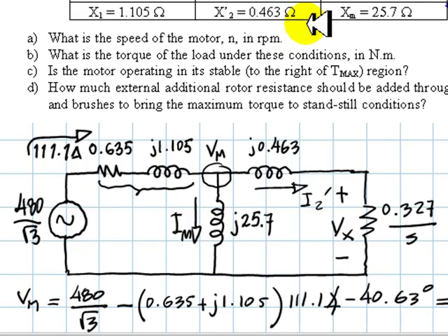The first thing I do in an exercise like this one is to draw an equivalent circuit of the one phase I will be working with. This circuit. I have copied the values of R1, X1, X2 prime, Xm, and R2 prime to the circuit. The applied voltage is, of course, one of the phases of a Y connection, the line-to-line voltage 480 divided by root 3. I will use this voltage as my phase reference, 0 degrees.